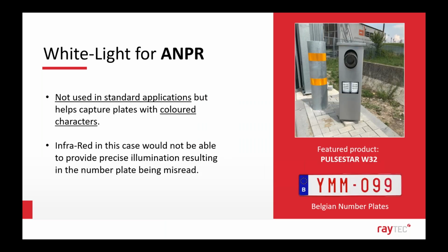So just to expand on that a little bit, while infrared, I'd say, is probably the most common choice, there are scenarios where white light is essential, and this is particularly true for plates with colored characters, as mentioned with the red lettering on a white background, where infrared wouldn't provide enough contrast for the camera to pick it up. This is where white light is a definitive requirement.